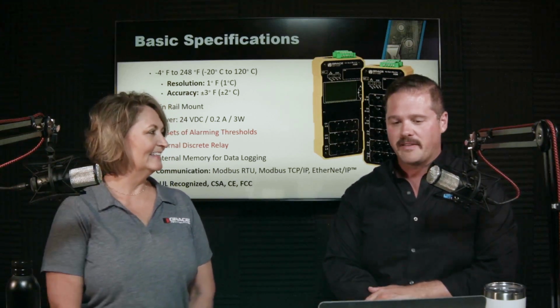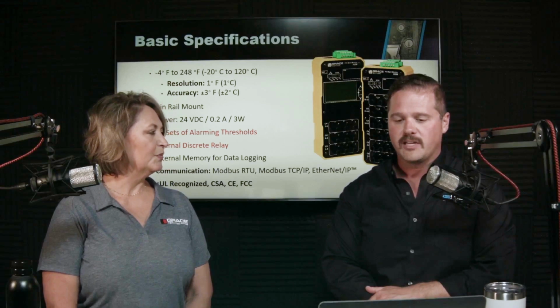There's actually a question on that from Nelson. Can you be notified via your phone of any issues that occur? Yes, you can, not directly out of the unit. The unit talks Modbus RTU, Modbus TCP/IP, as well as Ethernet IP.